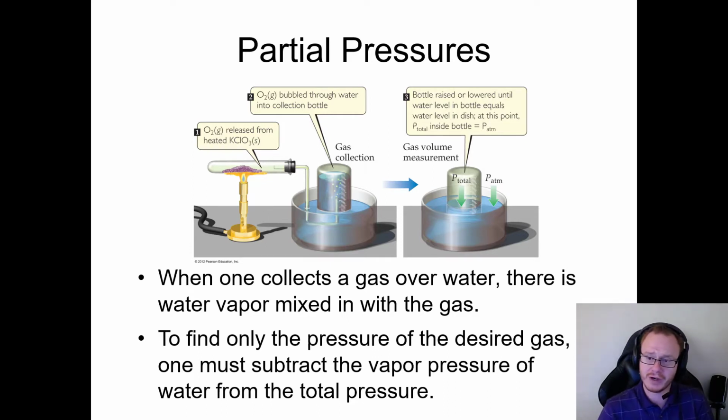But if we know that, we merely have to subtract the vapor pressure of water from the pressure inside the chamber. There are charts available for that, and I will provide you with that this week because we have a couple of questions that do involve you removing the water vapor pressure from the chamber.